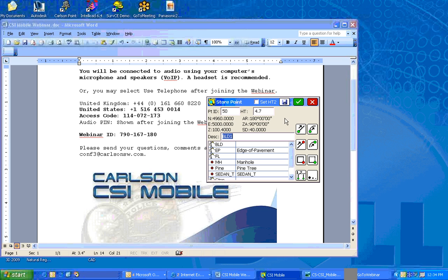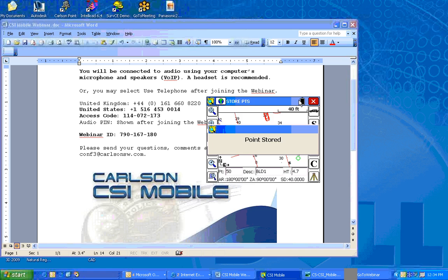And now I will say close the rectangle. I can just type space RECT or back up and use one of the icons. Actually, that's the wrong one. It's the green one. That's the rectangle. So because I did 3 points, it should close that rectangle.